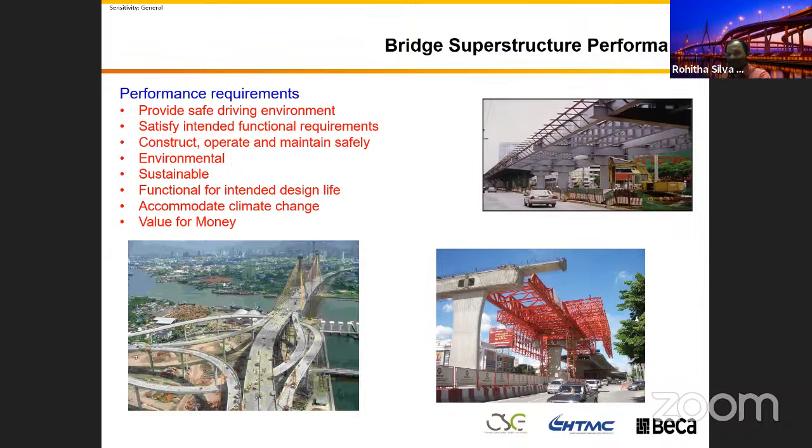In that, they specify the temperature differential you have to maintain, and in the particular concrete you need a certain amount of additives like fly ash and slag. They give the mix designs and even the temperatures. Then we durability engineers use Strand7, or else we use CIRIA, where you can input all those things. You can also calculate manually based on that recommendation. You can check that beforehand. Now we do that.